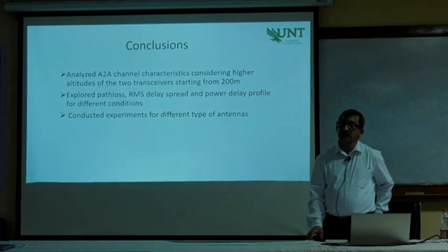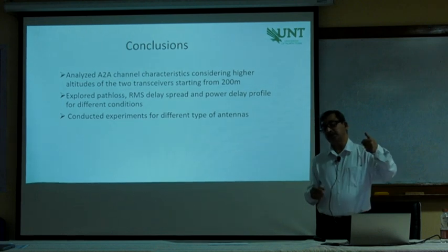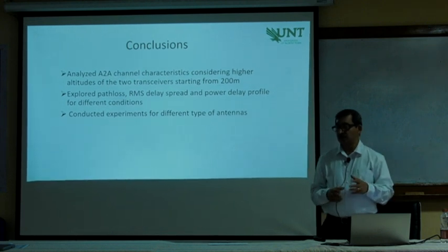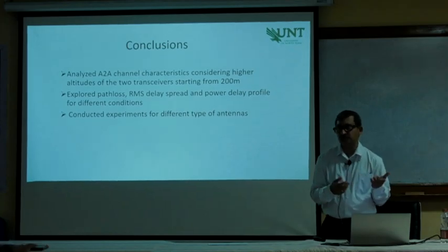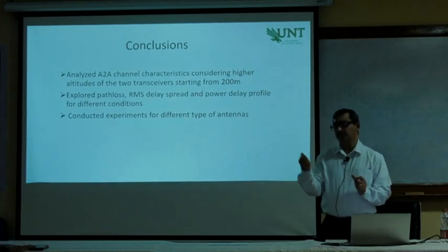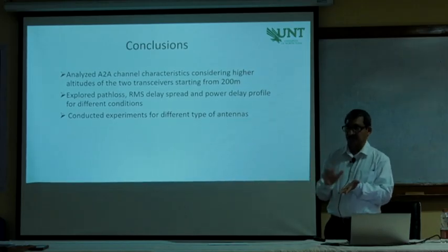Yeah, if you can increase the one hop distance, that depends on the transmit power. For example, in one experiment, we were trying to see how come the range is so small. All we had to do was increase the power. But of course, it has to be within the regulations.